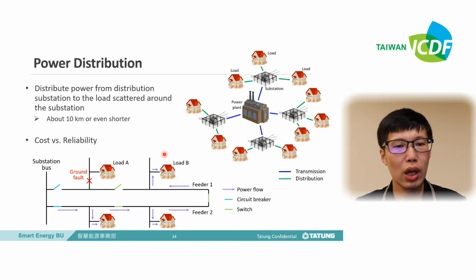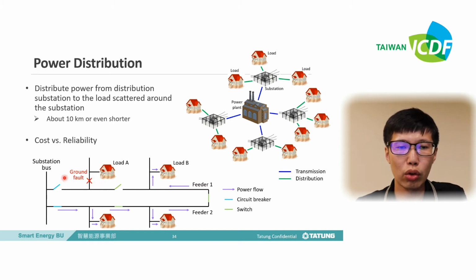And after the ground fault is eliminated, we can close the switch here and open the switch here and close the circuit breaker. Then it will transfer to the normal case.